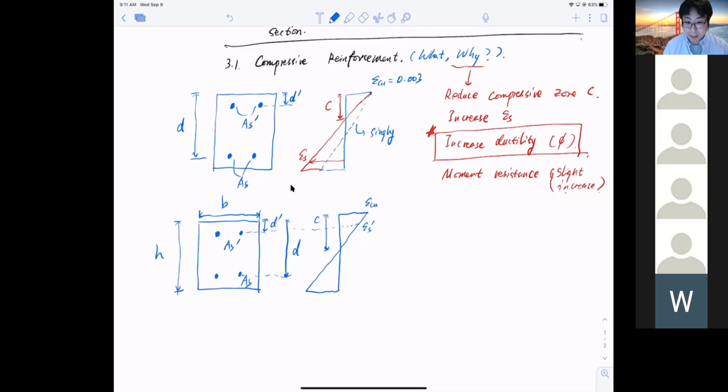Okay, so now look at the internal stress distribution. Draw the stress distribution like this. I have a stress from the steel, fs. Assume it yields. So the compressive block on the top should be a rectangular stress block with a stress of 0.85 f prime c. That's the width. And we have an effective compressive zone a, still beta 1 c. And that is the internal stress distribution.